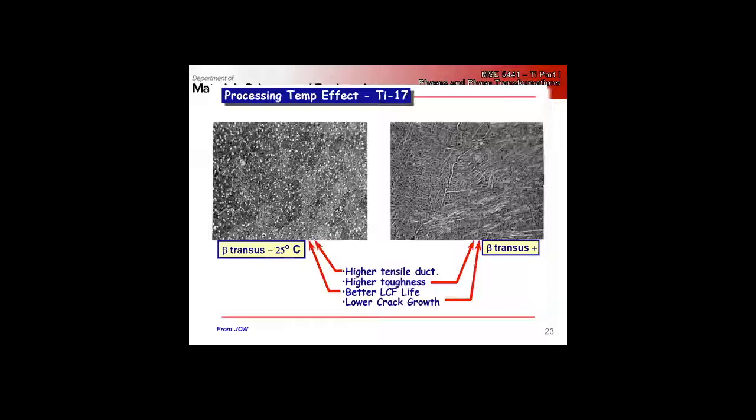If colonies are aligned with our slip direction, we've got nice long mean-free paths for dislocations. So we can think of a whole colony as being like a single alpha grain if it's aligned for slip. If it's not aligned for slip, then you have a strong Hall-Petch effect. But in the basket weave structure, we always have these long grains that, even if they are well aligned for slip, are completely surrounded by other regions that are not.